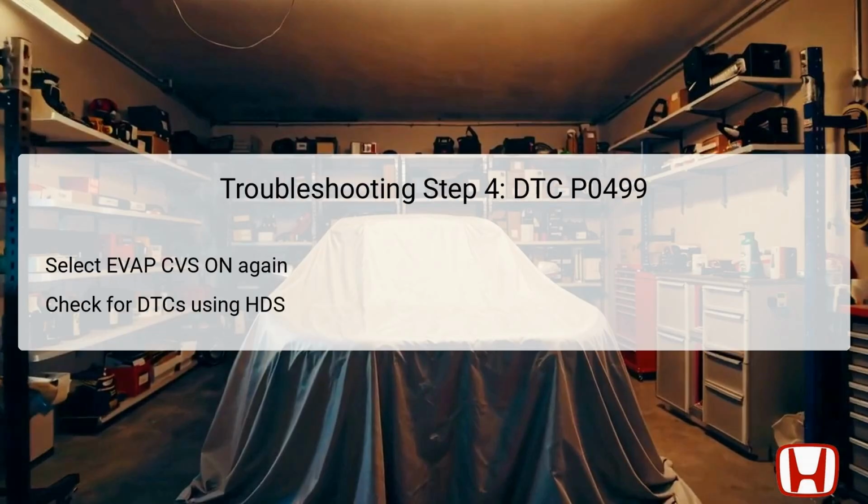Following the PCM update or substitution, the next step is to once again select EVAP Canister Vent Shut Valve, CVS, on from the HDS inspection menu. This step initiates a new diagnostic routine to closely monitor the EVAP valve's response after any changes have been made to the PCM. After reselecting, you must check if any pending or confirmed DTCs arise.